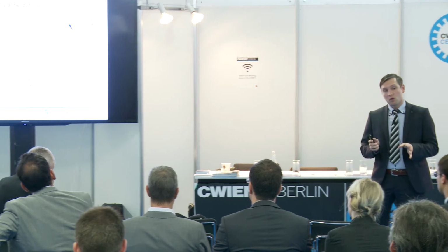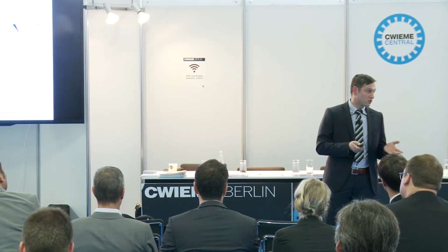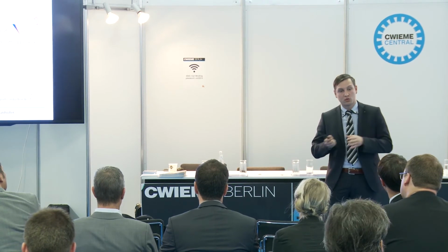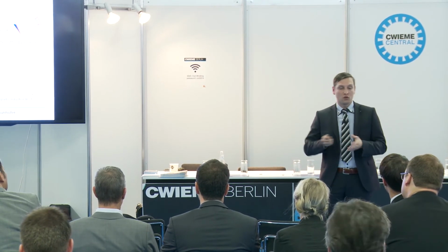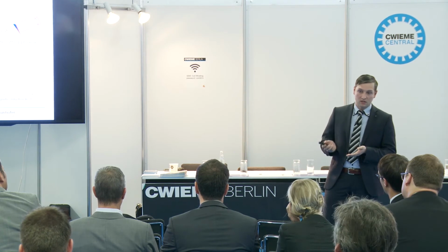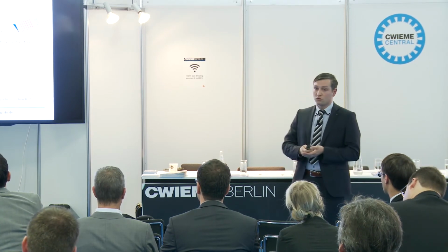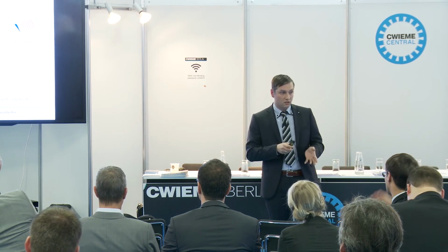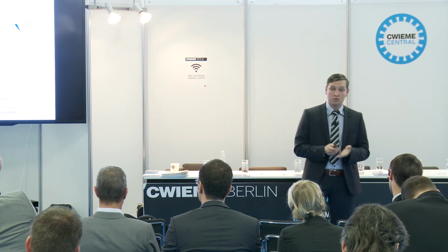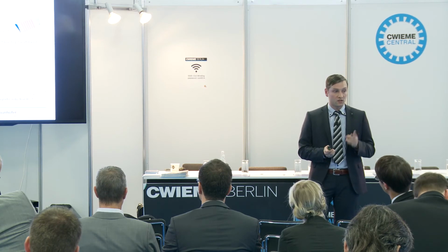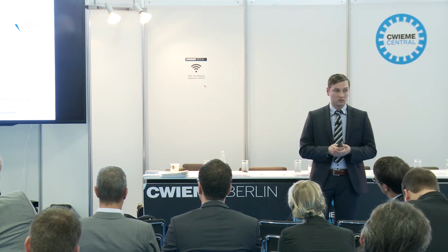The question now was, maybe we can have a process with the focus of high output and improved properties. And so we tried that laser surface treatment in order to modify the stress state in the laminations. And in the lab, we achieved an improvement of 10% in specific core losses.